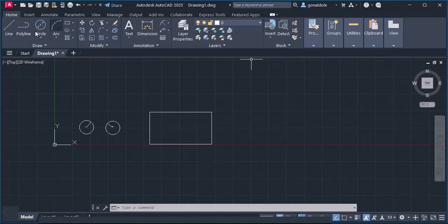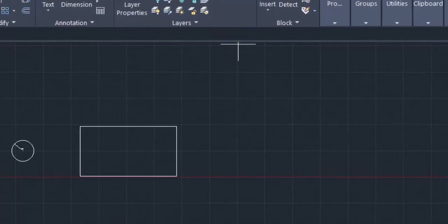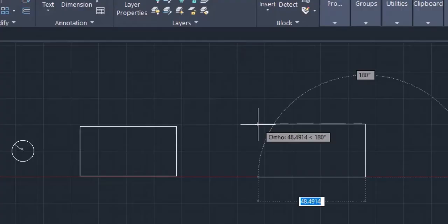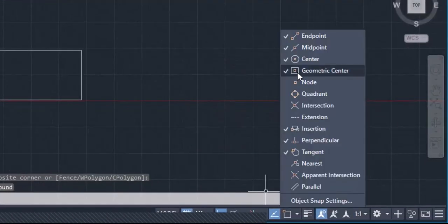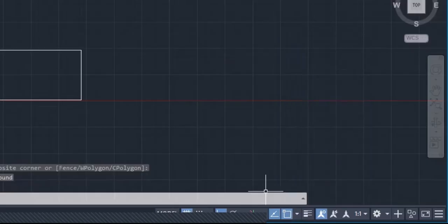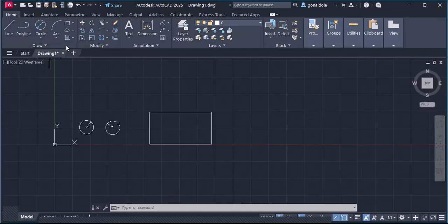And I'm going to click on Polyline again. And let's try to draw the rectangle. Then you would see the difference. Coming down here, now you would see if I move my cursor here, it's okay. The OSNAP command is not on. Sorry about that. So let's delete this. Then put on the OSNAP command. I only selected the points I want to snap to, then I have to select the command itself. Once this blue icon is on, it shows it's on. So I'm going to click on Polyline. Then let's try to draw the rectangle again.